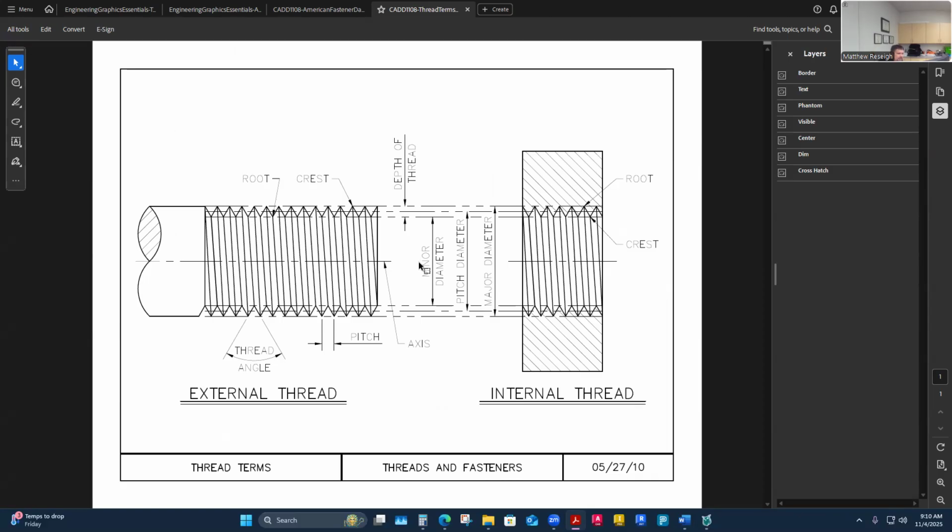So we've got major diameter, minor diameter, and pitch, the three things we've nerded out a little bit on. And why this is critical to know is that the way threads get cut, you have to start with something that's at least the major diameter in order to cut these threads, right? If you were going to make these threads, it's going to be a machining type process. They're going to start with a solid shaft, solid material that's at least as big as the major diameter so they can cut this.